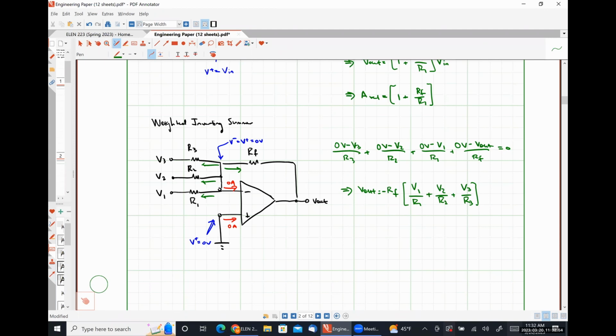So this is one way that we can add signals together. Now, technically speaking, you could also have a non-inverting summer. We could apply multiple input signals to the non-inverting side as well, but the math does not work out nearly as prettily as this does. Generally speaking, if you wanted the output of your inverting summer here to be positive, you would simply run this into a second amplifier stage that would just flip the polarity of the signal.